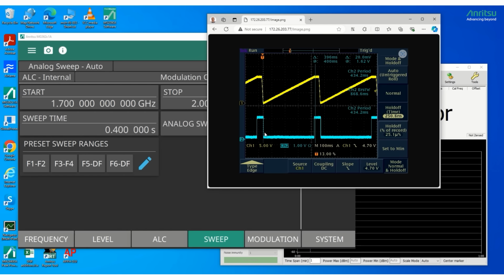Power sensor in scope mode should then show the amplitude response of our bandpass filter. This is going to be our measurement process. Let me connect the retrace blanking signal to the trigger input of the power sensor, and then we can go over to the power sensor GUI to set up the amplitude response measurement in scope mode.